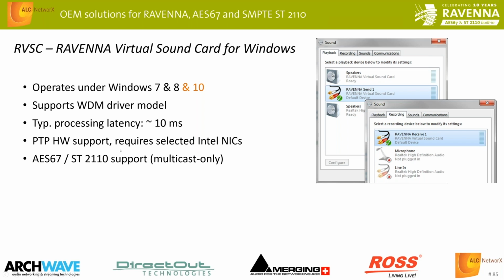However, there's one particular specialty you should know. Our virtual sound card, unlike others, unlike the Merging sound card, and also unlike the sound card being offered by Lawo, only works when a particular Intel network chip is present. The reason for that is that we have just translated our Ravenna design, which works with hardware timestamping support, into the Windows system area, and Windows doesn't know anything about PTP at all. So we have looked for a particular chip which is able to support PTP hardware timestamping. We identified a number of Intel chips which can actually do that, and so we require one of those chips being present. Otherwise, we don't have the PTP timestamping, and the Ravenna virtual sound card cannot run properly.